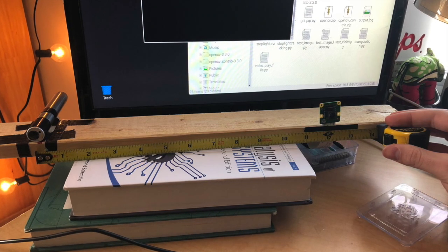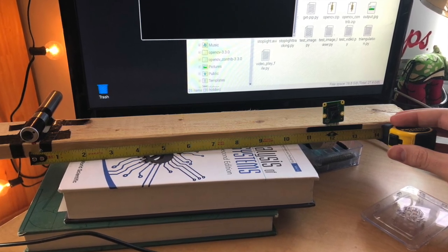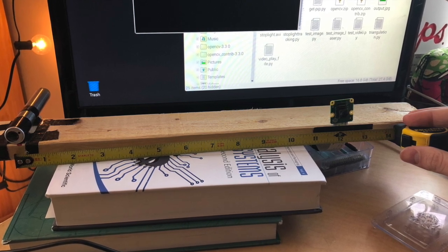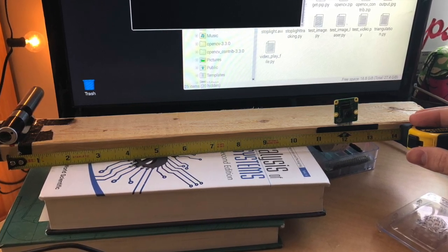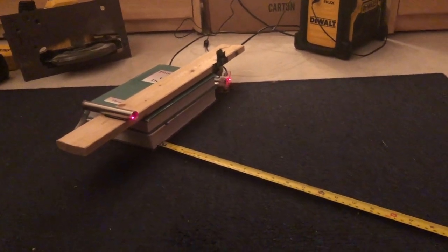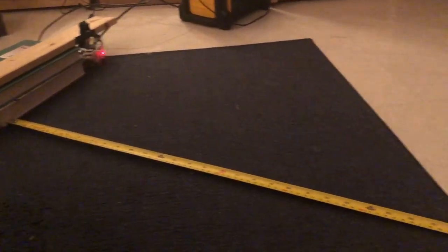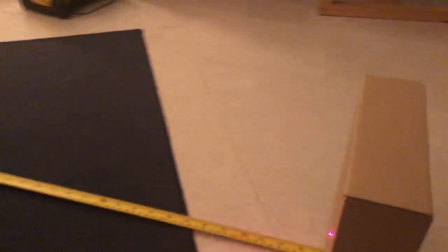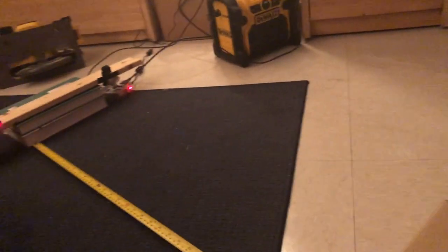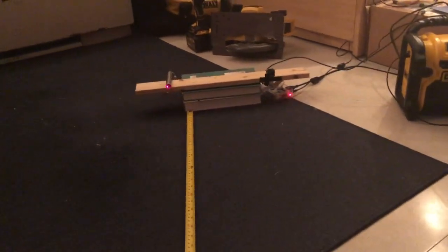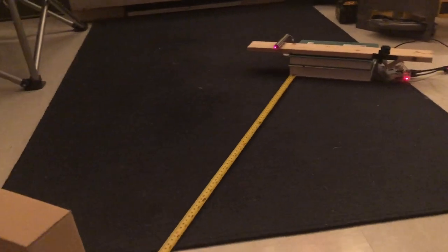For sensor testing and calibration activities, we first started with a LiDAR that consisted of a red laser pointer and the Raspberry Pi camera. The first calibration was to take photos of the red laser pointer on a box at known distances away. At each distance, the Raspberry Pi takes a photo of the red laser pointer and calculates how many pixels away it is from the center of the camera frame.